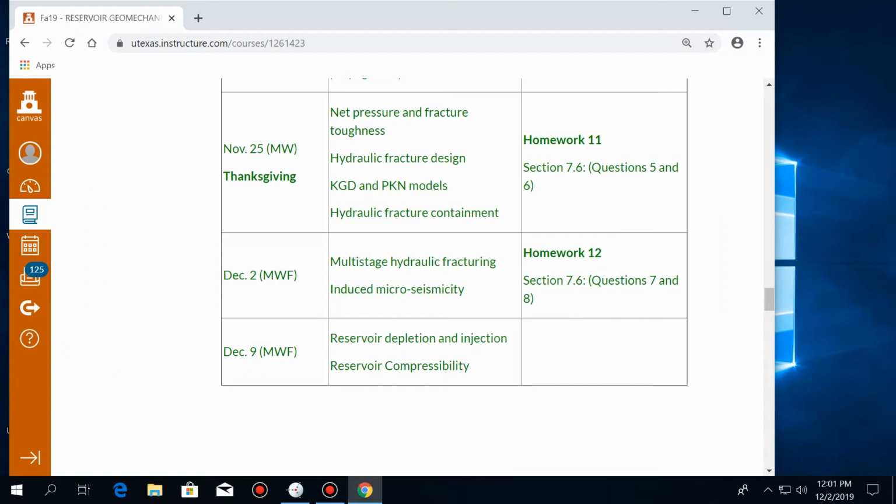But at the same time, you need to know the basics of, for example, how to calculate a vertical stress, a horizontal stress, a pore pressure if given an overpressure parameter. You need to know also in a wellbore in which location you would expect to see a hydraulic fracture or a breakout tube. That I think you did very well in the previous exam. All of that basic knowledge, you have to know that for the third exam. But I'm not going to ask you details about the previous ones.